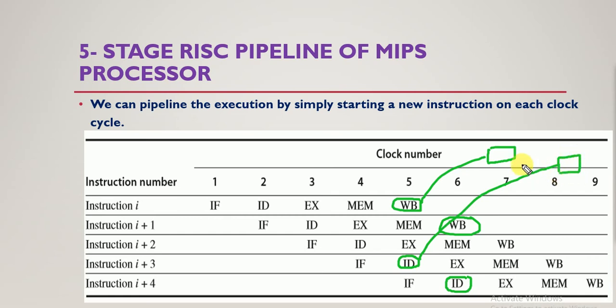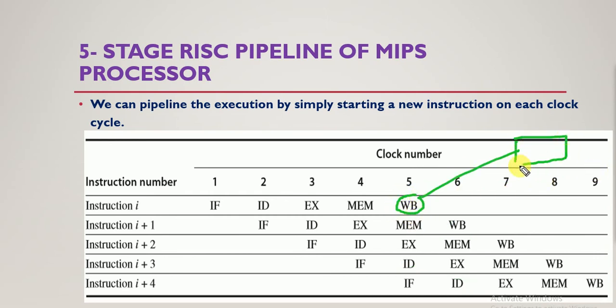This is the register file, a common area for reference to each register. Each register's details are taken from the register file. So write back refers to the register file and instruction decode also refers to the same register file. This is a single resource, so these two cannot be done at the same time.